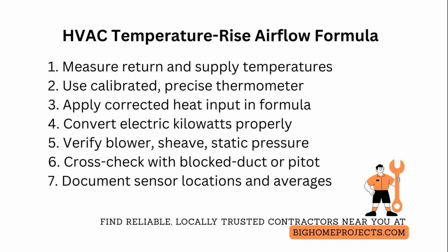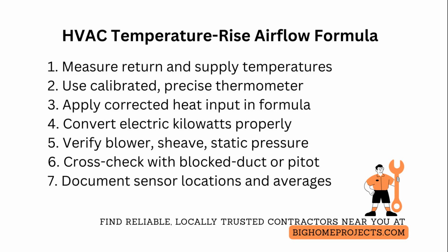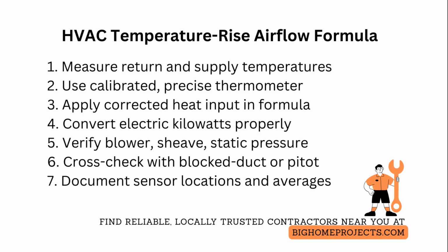Before leaving the site, perform a functional sequence and monitor return air temperature for at least 10 minutes to confirm the system stabilizes and the measured performance holds under operating conditions.